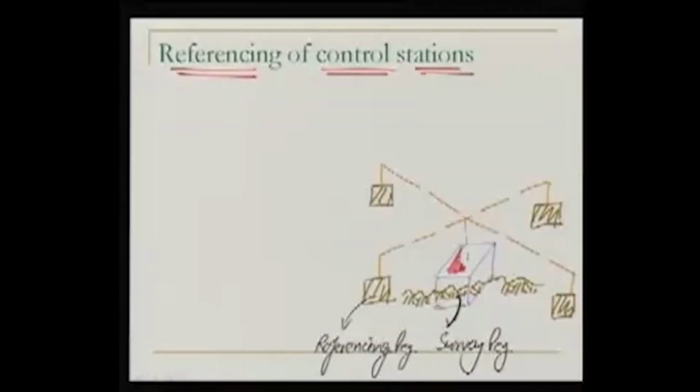This is a concrete block, and this concrete block is embedded there on the ground, and when this concrete block was established, that's the point of the station. Along with this, we establish some more stations, or rather some more concrete blocks. What they serve is, if I stretch some thread between these 2 points, it intersects exactly over the station.